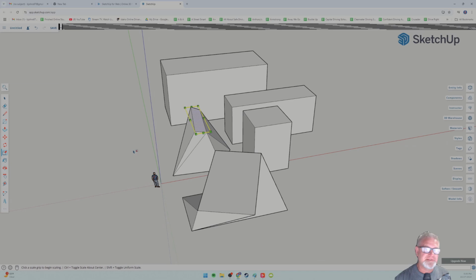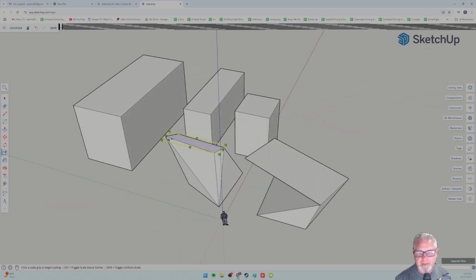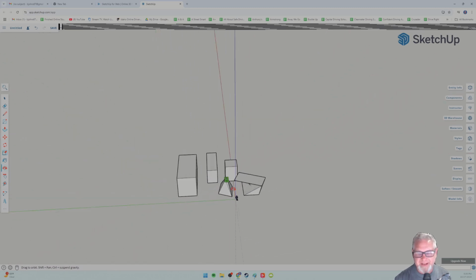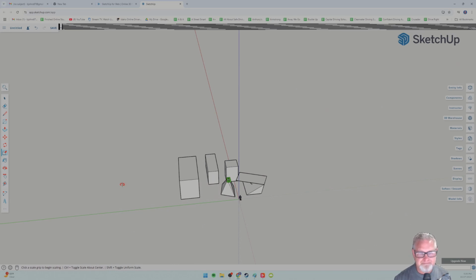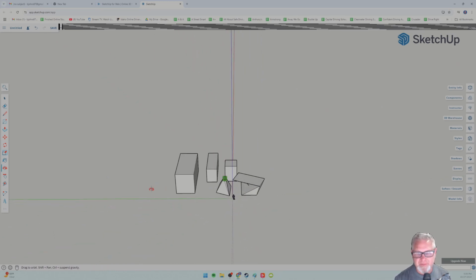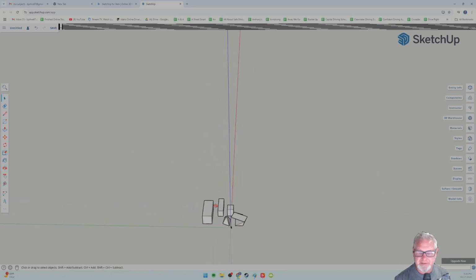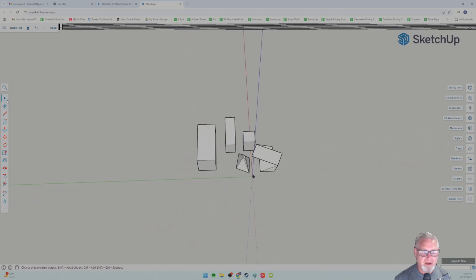So you've probably used a similar tool in Paint or some kind of paint program. And it's getting pretty close to a pyramid, but not exact. Normally you would scale something when the whole thing is selected. So let's go ahead and do that right now. I'm going to use the select tool, and again, I recommend you follow along. I'm going to just draw a box. Make sure you don't touch anything else because we're trying to select just one shape. So you might have to rotate, zoom out, zoom in. You might even have to pan a little bit. I like to be kind of top view so I can draw a select box just around one shape.